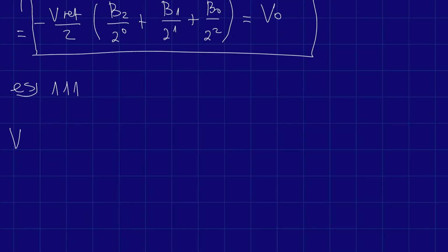And let's see what the maximum voltage would be in our specific case. So first you need to understand why this right here is the resolution. Vref is our reference voltage, and n in our case is the number of bits. If we do 2 to the n, we will see the number of values we can have with those bits. For example, let's say we have only 2 bits.